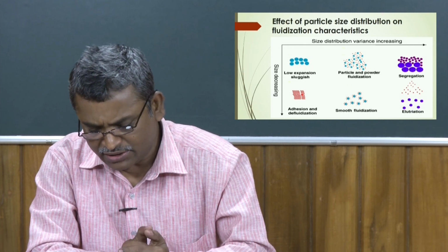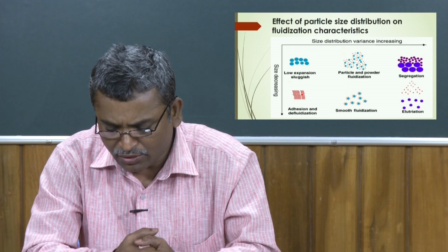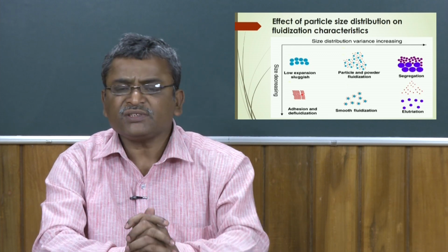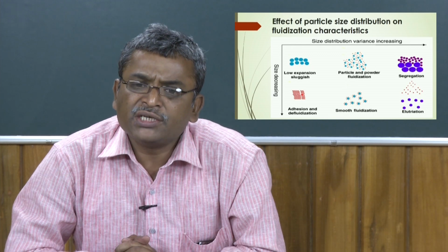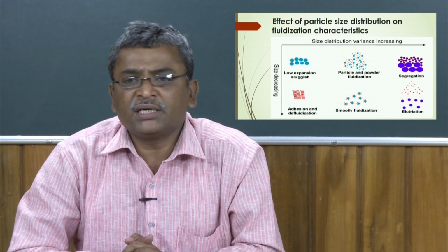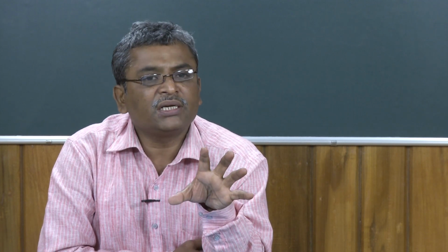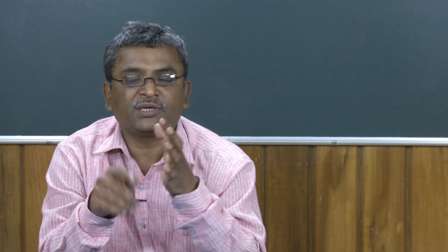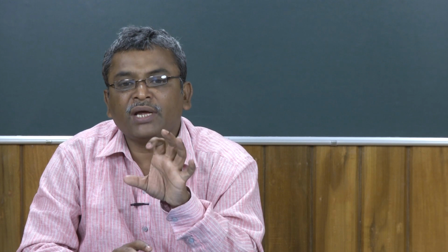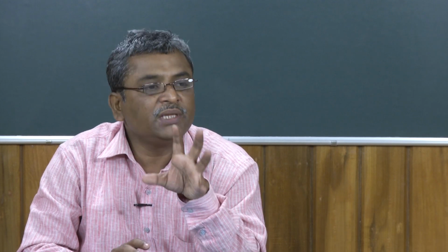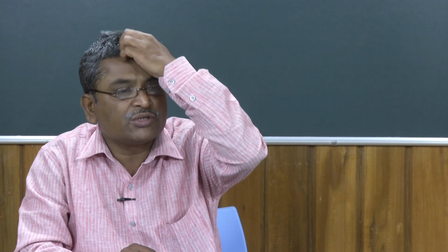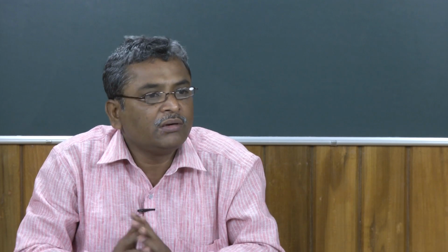Sometimes elutriation is very important here. In that case also you have to know how much elutriation is possible from the bigger particles. Or if you initially use all bigger particles, and after elutriation, after the particles are broken down, you analyze how much of the solid particles has been broken down and what the size distribution of that is, then from this you can at least interpret what the elutriation rate and the elutriation efficiency should be.